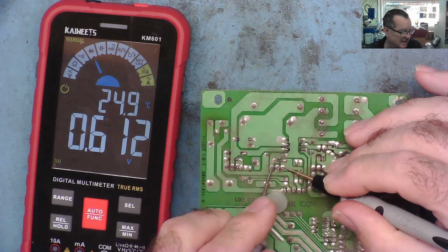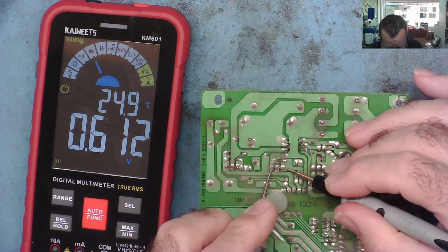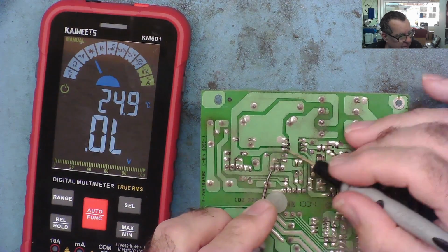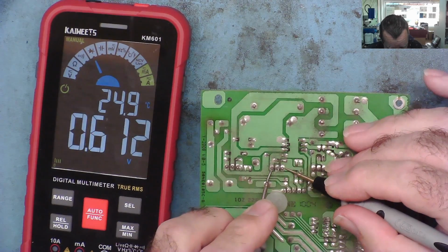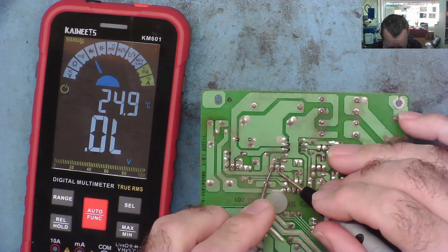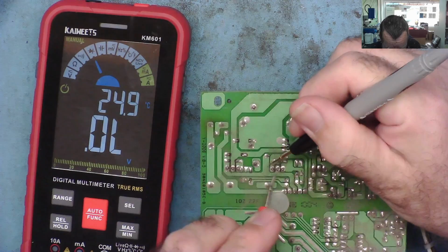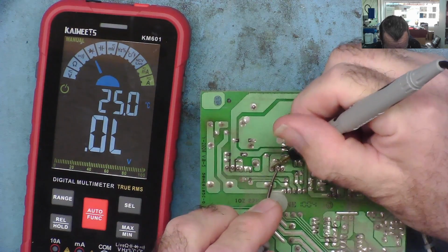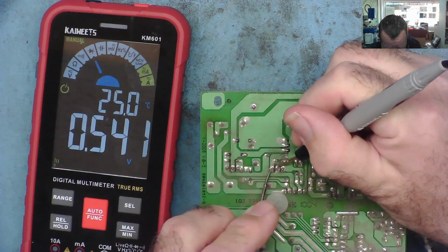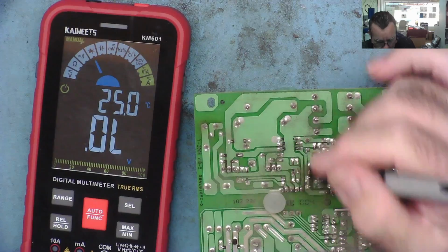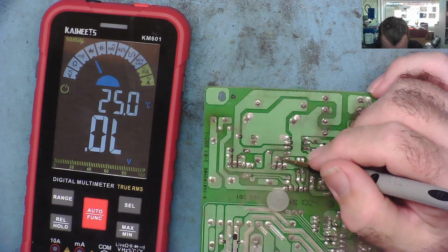We see a reading here, another diode junction. Now that is almost certainly due to another component around here that's causing that reading. And again, we see them between the collector emitter, but not that way. So you're tending to see more diode junctions than you would expect on a transistor.